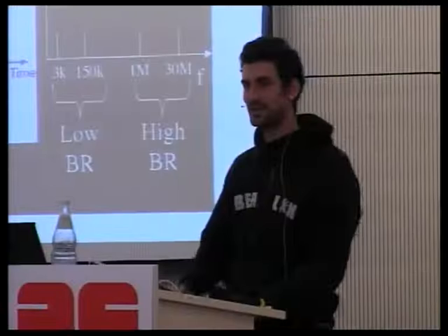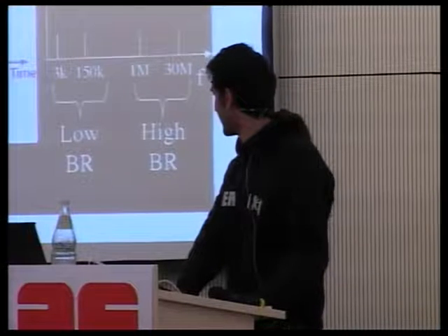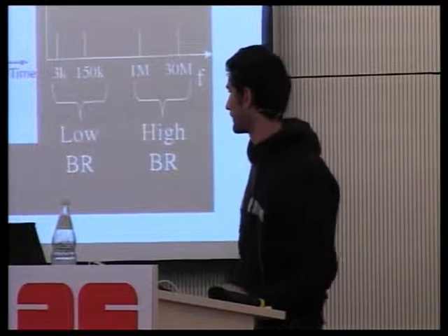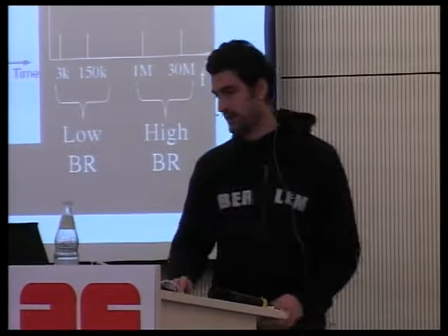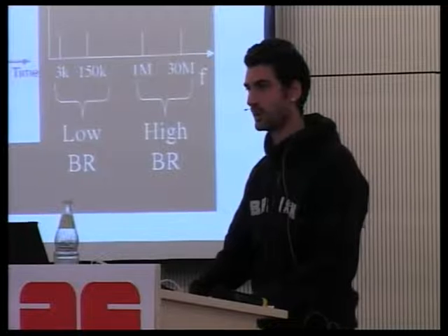In light, you have what we call high bitrate technology. This technology is using the 1 to 30 megahertz frequency band, this part. And in light gray, you have some low bitrate power line. I'm sorry for the quality of the schematic. The low bitrate is using this band, which is the 3 to 150 kilohertz, which holds less space for bandwidth and bitrates. So we will target high bitrates.